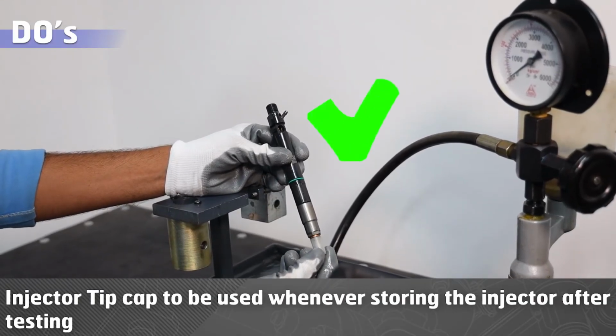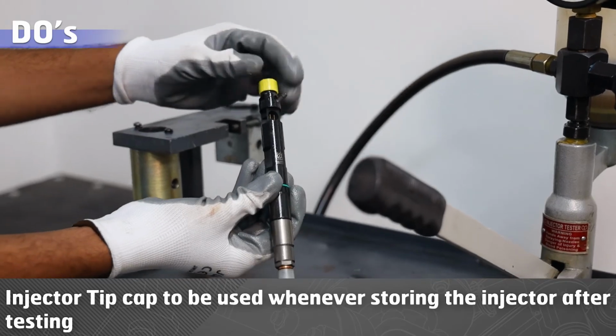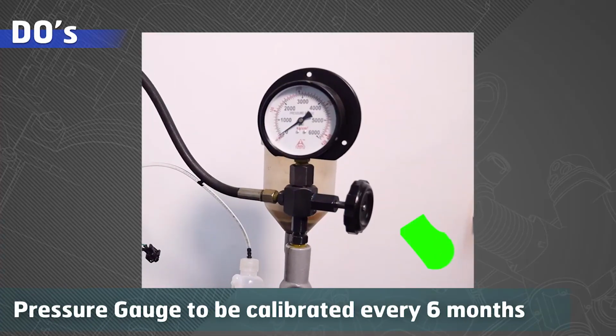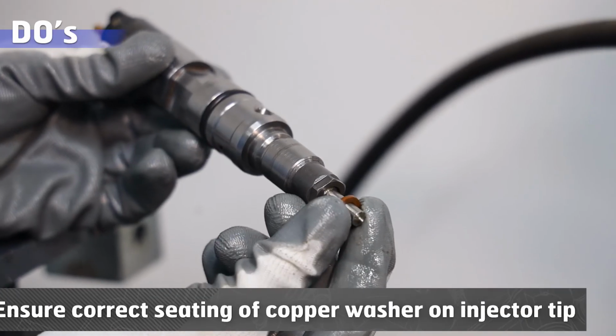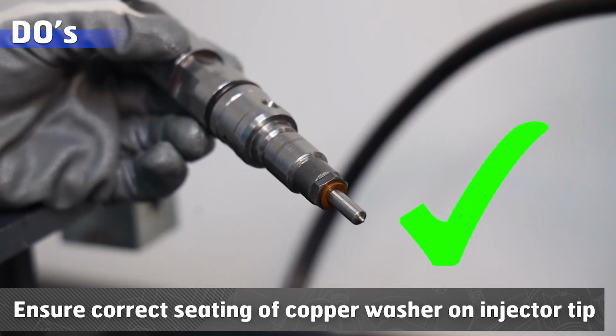Injector tip cap to be used whenever storing the injector after testing. Clean up fuel spills immediately. Pressure gauge to be calibrated every 6 months. Check fuel filter 5 micron at every 6 months. Ensure correct seating of copper washer on injector tip.